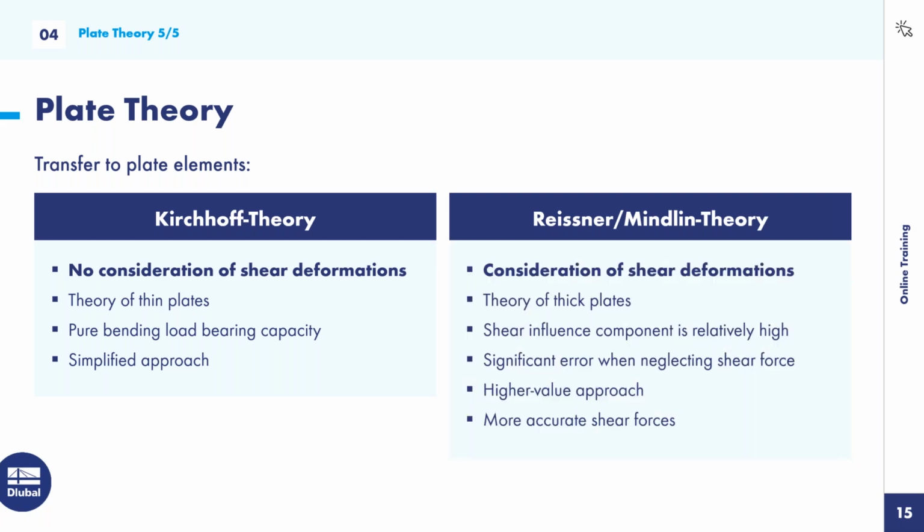So Reissner-Mindlin theory, on the other hand, is great for thin plates and thick plates. The thicker the plate gets, the bigger the delta you'll see in the difference of results, and the more inaccurate Kirchhoff's theory becomes because of the shear deformations. The effect of shear deformations will greatly affect the thicker plates. In my opinion, the Reissner-Mindlin theory should just be used by default, but it's just good to know the difference between the two.